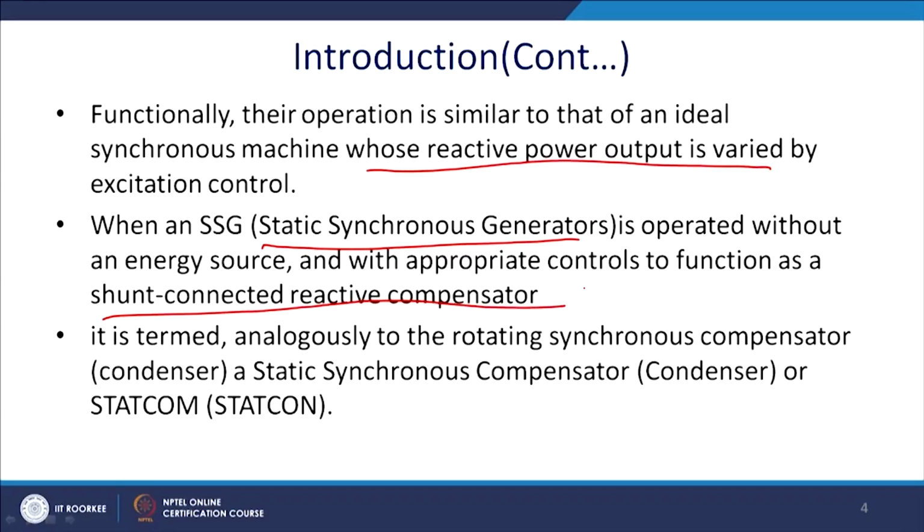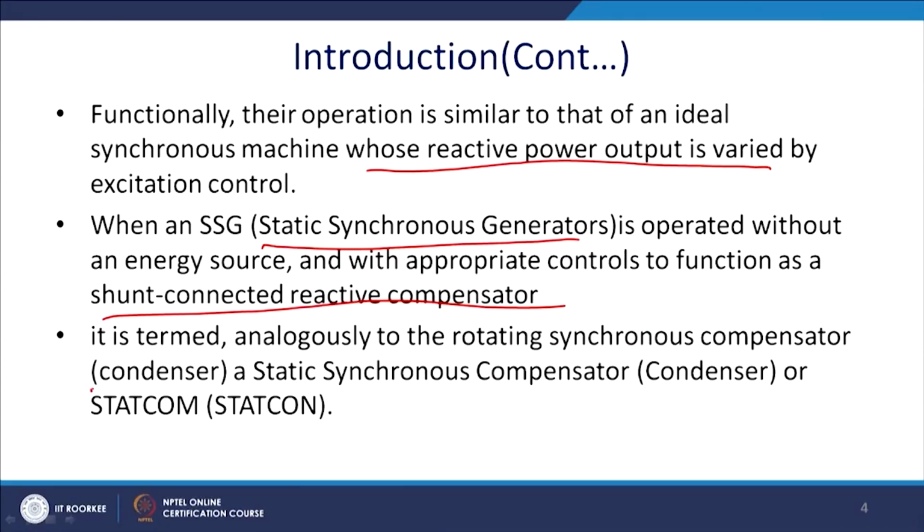You have to rotate the system at synchronous speed, so a huge amount of energy is consumed. Thus you see how the terminology STATCOM came. Analogously, the rotating synchronous compensator or condenser and the static synchronous compensator have been coined together and STATCOM is formed. So, essentially it is a stationary over excited synchronous condenser.